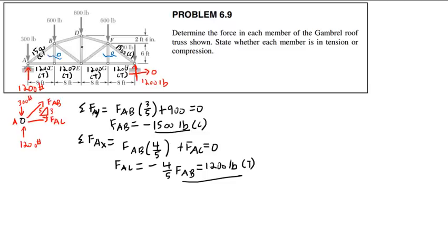So we are quickly seeing the behavior here. What is happening is that this truss is acting like a large beam. The top chord, a string of members is called a chord in a truss, is in compression, and the bottom chord is in tension. That's typical of truss behavior under positive bending. We'll learn what positive bending is later, but generally positive bending is a beam that bends in this kind of shape, while negative bending is a beam that's bending in that kind of shape.